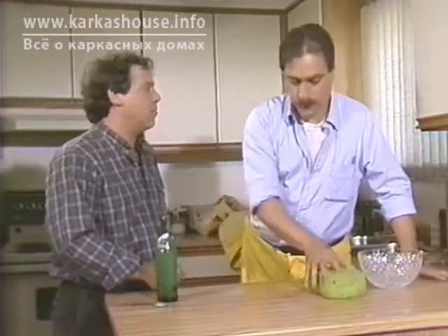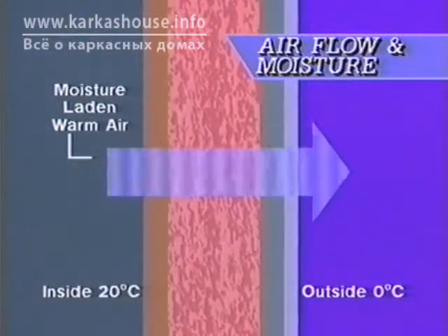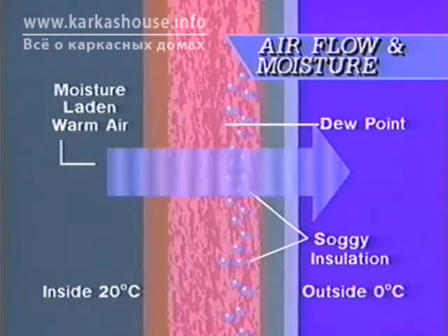Well, all around the house, I guess, when you're having your shower, on the cold bathroom window. Precisely. Also in kitchen windows very frequently and a number of other places. Nice basic science lesson. What's it got to do with building houses? Well, to stop condensation, we have to stop water vapor from getting into a location where it will cool. We need to keep the vapor out of the walls.